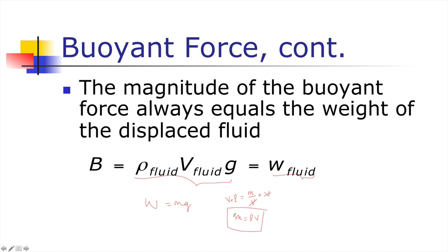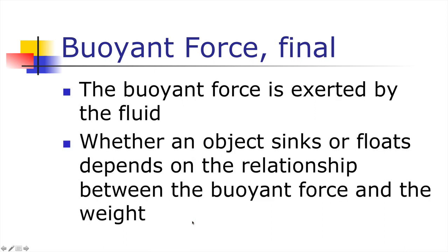Then you substitute that in place of m, and you get weight is equal to density times volume times gravity. So the amount of buoyant force that any object experiences is the same as how much fluid you are going to displace. Buoyant force is always exerted by the fluid. Whether the object sinks, floats, or partially floats, it experiences buoyant force.